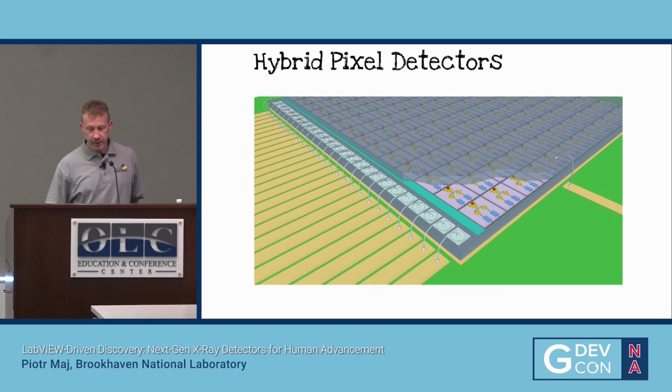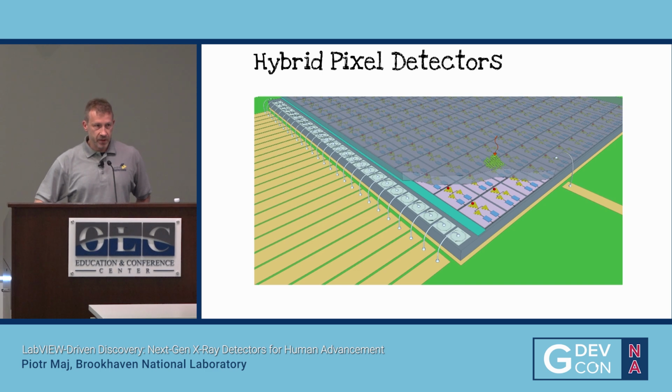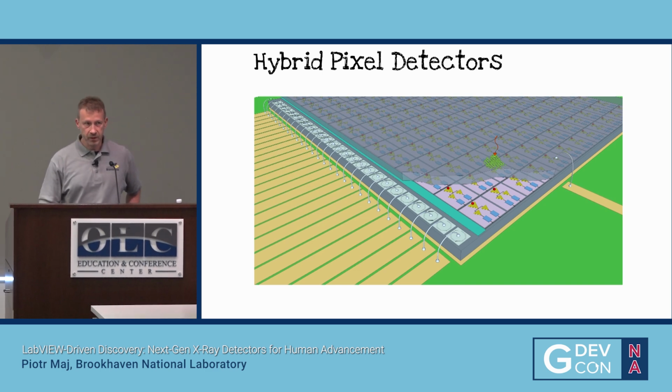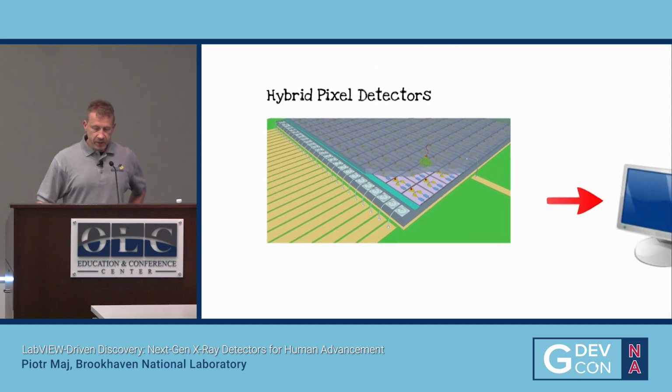power and data. When the X-ray photon hits the sensor, we want to collect this cloud of charge. The cloud of charge, roughly 2,000 electrons, is our input signal, the current pulse. We have to measure it. There's no device you can just buy. You have to implement it, build it. And then we read the data into the PC.